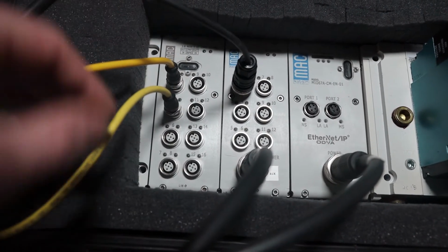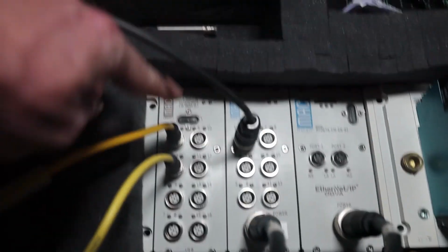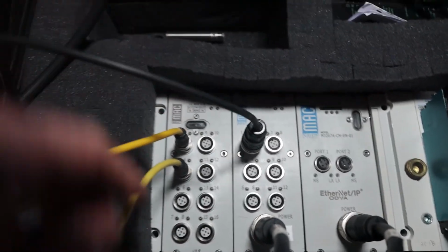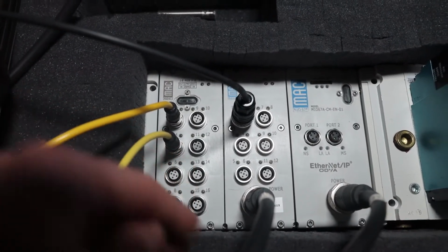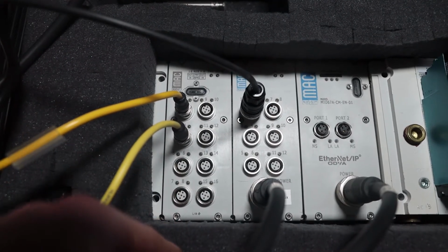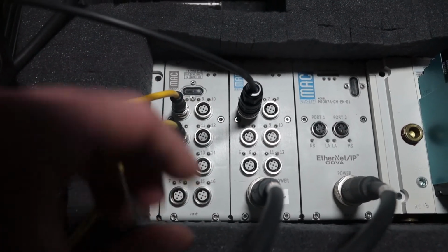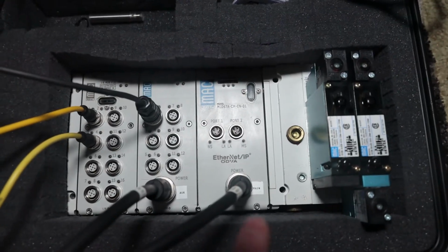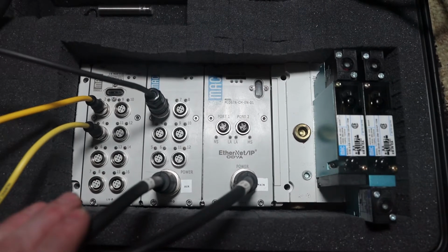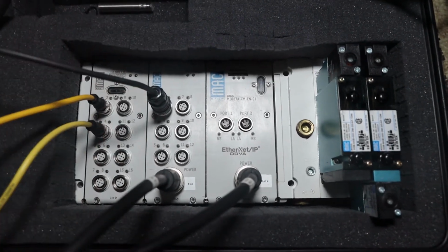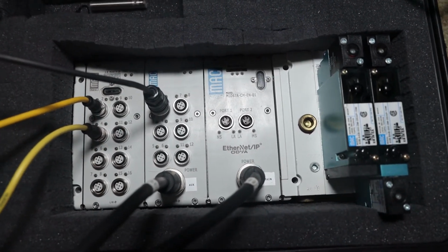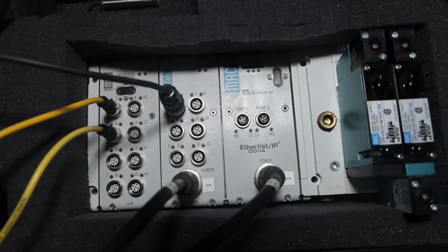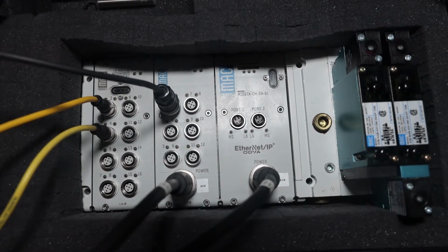or NPN. And there's dip switches inside of this right here where you can open that up and look in there, or there's also a place in the web browser where you can look at this as well, and it will tell you how it's currently configured. So hopefully seeing the layout of how these are laying out and seeing the software side of things, it'll make sense how we go about configuring these different modules and setting up the AOI instructions.